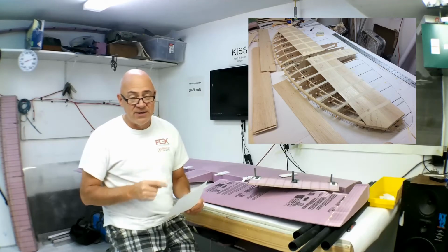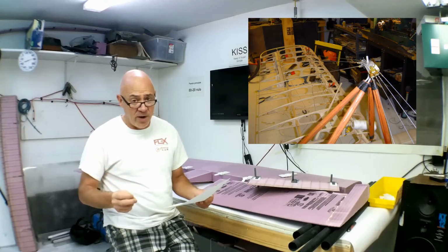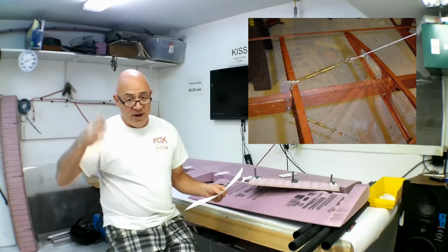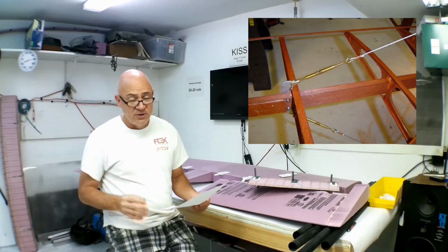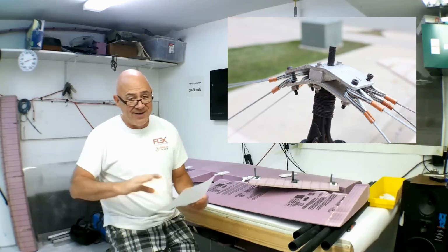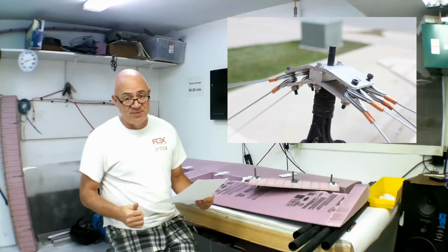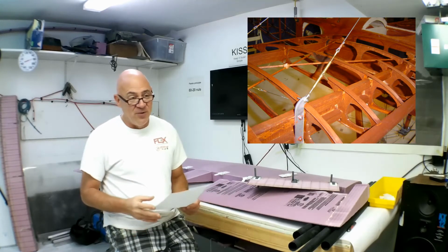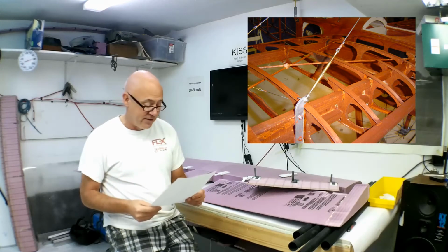Now, one thing I didn't really touch here is flying wires. If you're building a vintage airplane, those flying wires become your spars. My MSL-1 had no spars run through the fuselage and no spar ran through the vertical stabilizer into the fuselage. Only the flying wires held that airplane together. So you do need to think about that, but I'm not going to cover that in this because I used real hardware and real aircraft cable from aircraft spruce. I used all real hardware on that airplane. So that was the strongest part and most expensive part of that airplane, the hardware for the flying wire.